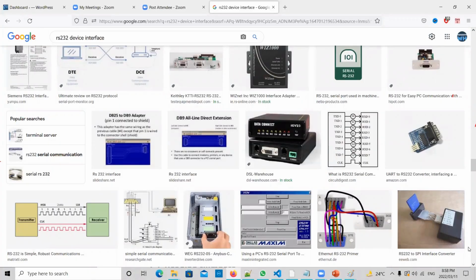What this flashing software used to do is take your executable code and transmit it in serial communication. It will simply send it byte by byte from the PC to that microcontroller. There is already an available code inside the microcontroller. It will simply take that code and write it into the memory. So when you want to exchange information between devices, you need a communication channel.